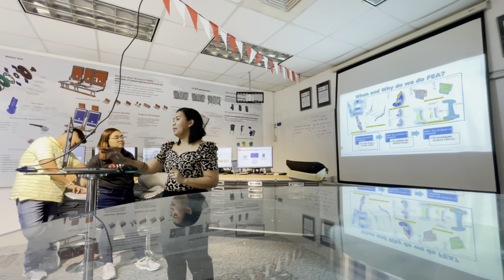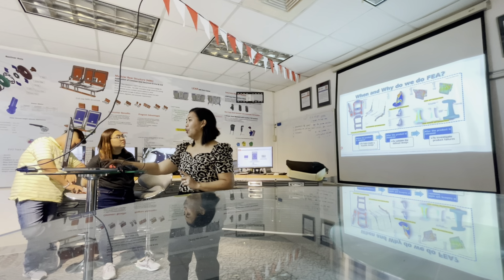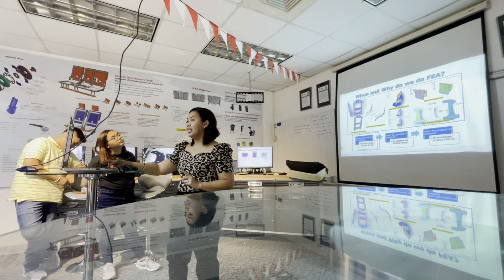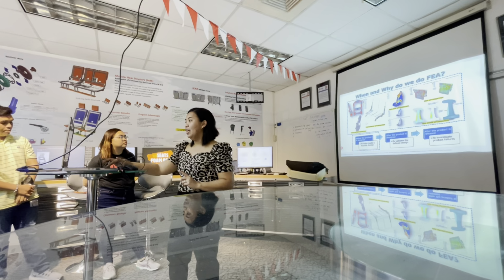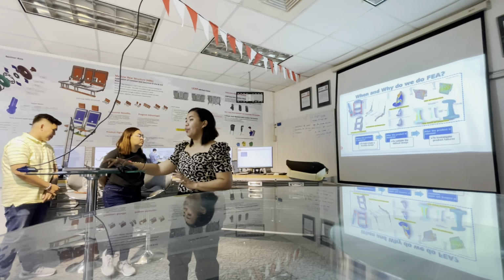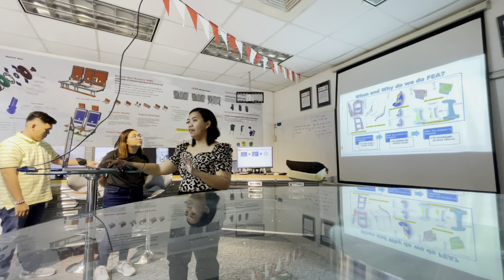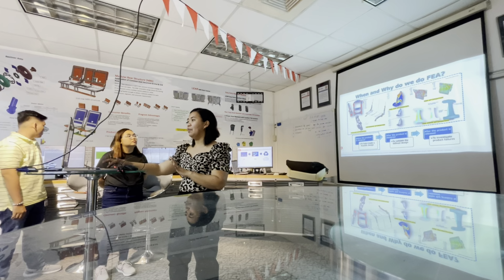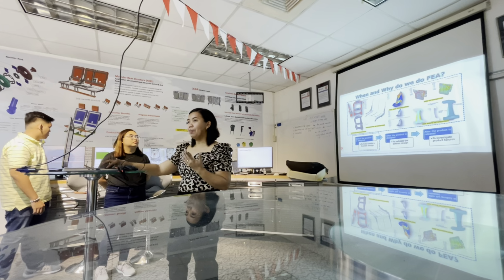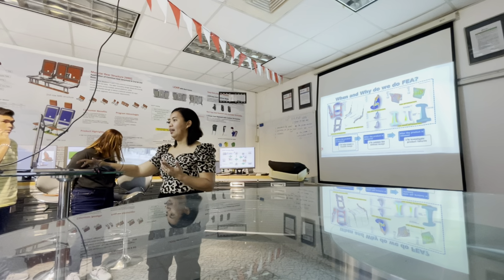So the other optimization that we do is size optimization, wherein we are trying to optimize the thickness for these rib parts. Like for example, this one, it's a plastic back frame. So each rib here, we are trying to optimize what will be its optimum thickness so that we can achieve a certain level of stiffness. Because as you can see, this red part, it appears to be weaker compared to this picture here.